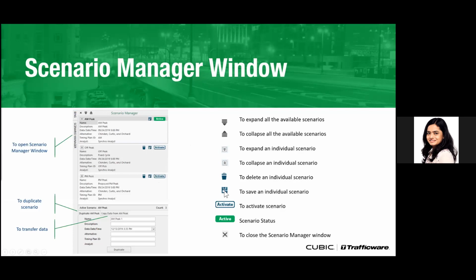Another important thing here is the save dropdown. We call it the save individual scenarios, the save scenario button. That means if, let's say, you are working in a large group and you have a base file, but you want to separate the scenarios to each of your colleagues.